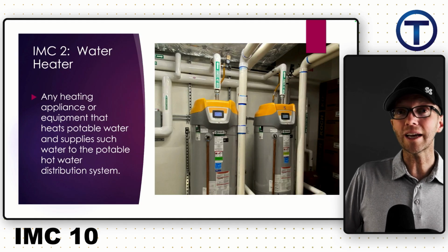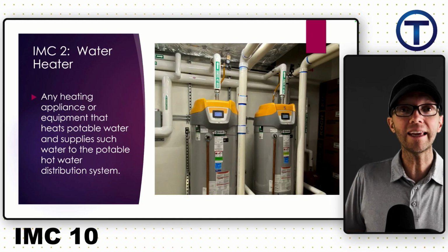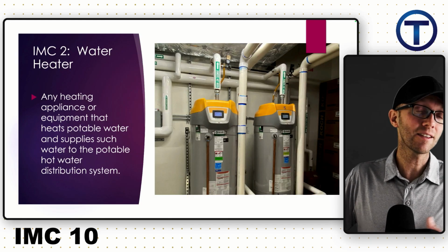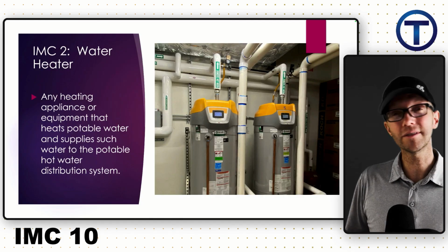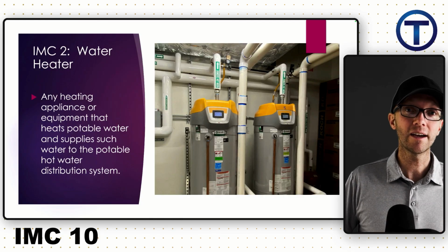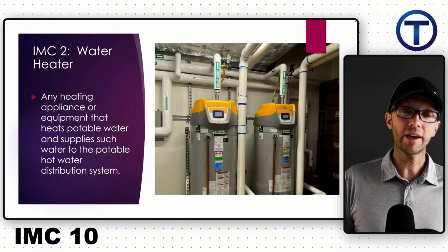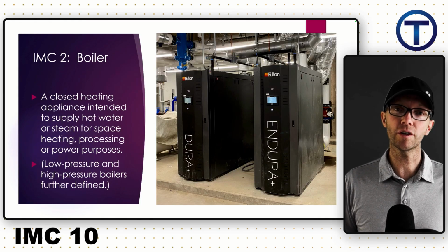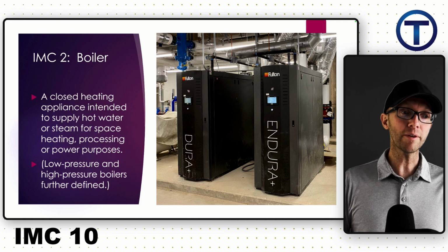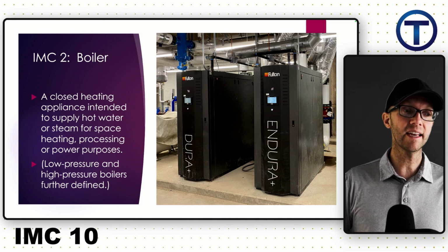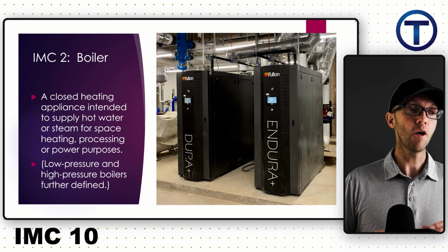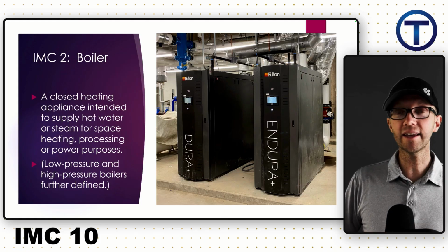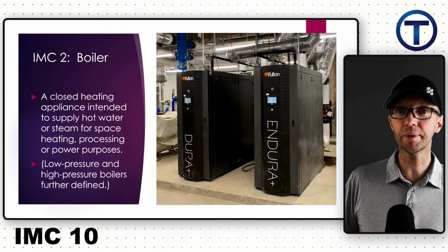You can use a tank-type water heater to heat space. And so then, is it a boiler? Not so much. But generally, water heaters heat the potable water, right? Compare that with the definition of a boiler. A boiler is a closed heating appliance intended to supply hot water or steam for space heating, processing, or power purposes.